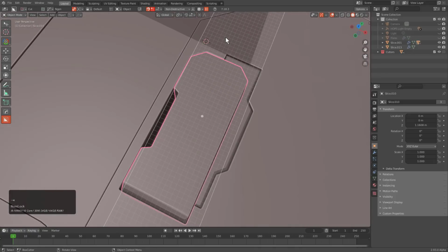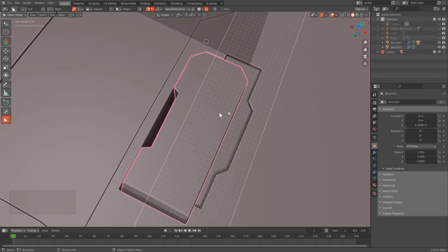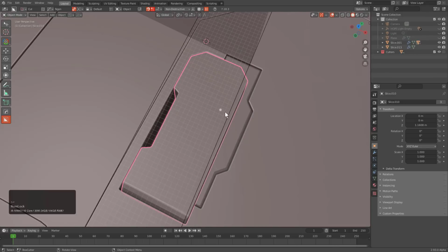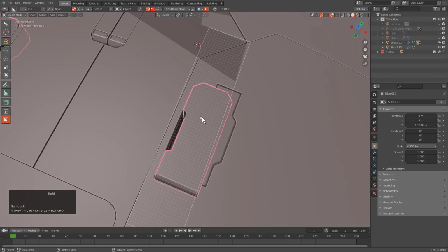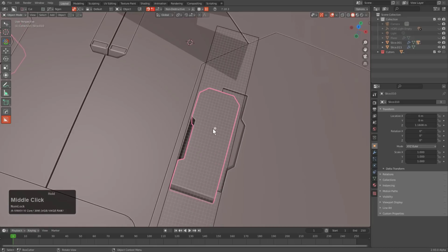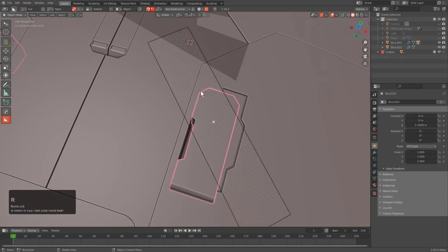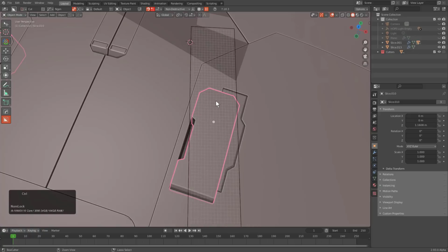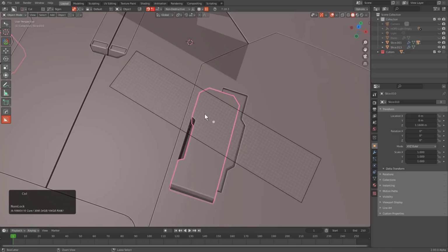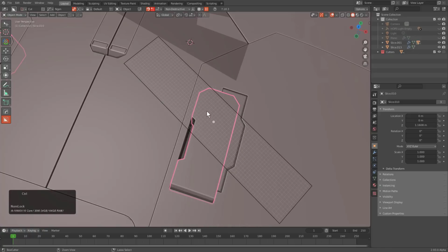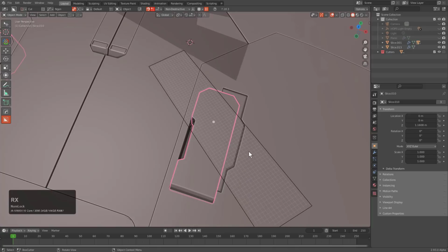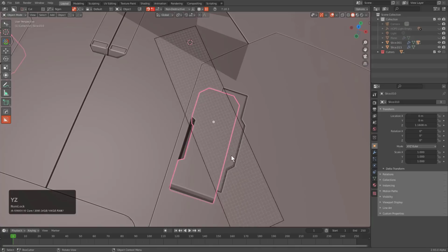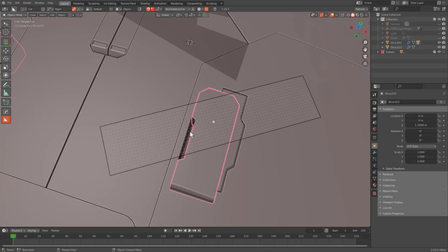In fact, you could press Tab in order to unlock the grid and be able to freely move it around, or you could even press spacebar to lock and unlock the grid just on the fly. Another interesting thing about this grid is you can press R in order to rotate. You could hold down control during rotate in order to do fine rotation or moving it on certain degree increments. You could press R and X, Y, and Z to rotate it as you would normally expect.